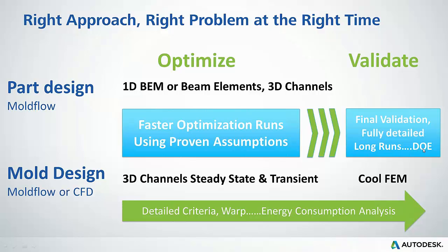And again, maybe I don't go outside Moldflow, and there are some statistical methods that are growing, as far as usage and as far as capabilities, or DOE approach. But no doubt when you get to this point, you've added all your detail, and it's going to be longer runs, and it may be multiple runs. It will be if you're optimizing, right? Whether you apply DOE or you're just doing a corner approach or a two-variant approach.